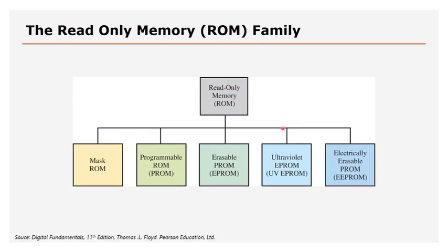In some of these cases, I'll discuss that, it is possible to reprogram it, but especially the first two, you cannot reprogram it. You program it once, the mask ROM is programmed once, and the programmable ROM is also programmed once. And once it's programmed, you cannot reprogram it again. So this one was normally programmed in the factory. So you as the designer or developer would send the program to the factory, and they would program it.